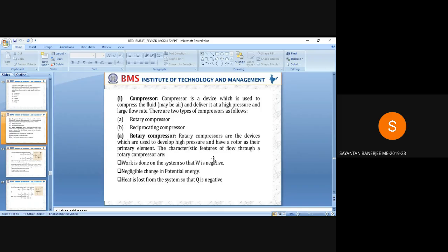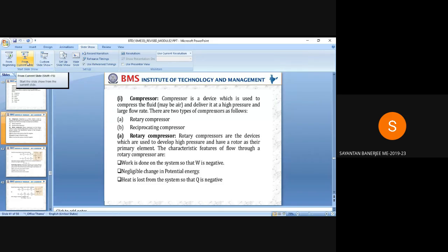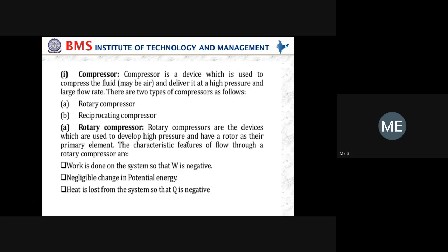Suppose there is a pipe, and in the beginning of the pipe there is a very large cross sectional area, and at the mouth of the pipe it has a very tiny cross section, and a steady state flow of air is happening through that pipe. Naturally, because of the equation of continuity, at the mouth of the pipe, the velocity of the air will become very high compared to the velocity with which it is entering, to ensure the volume flow rate remains steady. Because the velocity is very high at the mouth, the pressure will decrease, correct? Correct. Pressure exerted by the air will decrease. So at what speed should that air travel at the mouth so that it becomes compressible in nature?